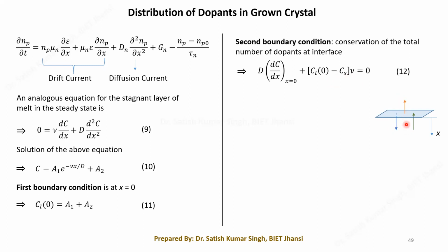Now if it is going away, then we have to see whether anything is coming to this particular layer. Is there any dopant coming to this layer? The answer is yes. It is coming from the bottom melt. There is a confusion if you exactly see the picture, because when we grow the crystal, the growth of the crystal will be in the x direction. So exactly the melt never comes up. The melt position is actually going down, so remember that.